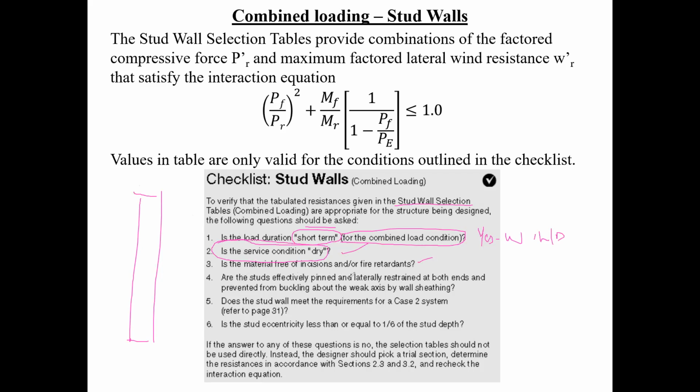Are the studs effectively pinned and laterally restrained at both ends? By putting a plate here and plates up here, and making sure the plates are well connected to the trusses and to your foundation, you can safely assume that it's going to be pin connected. So you can say yes to that.